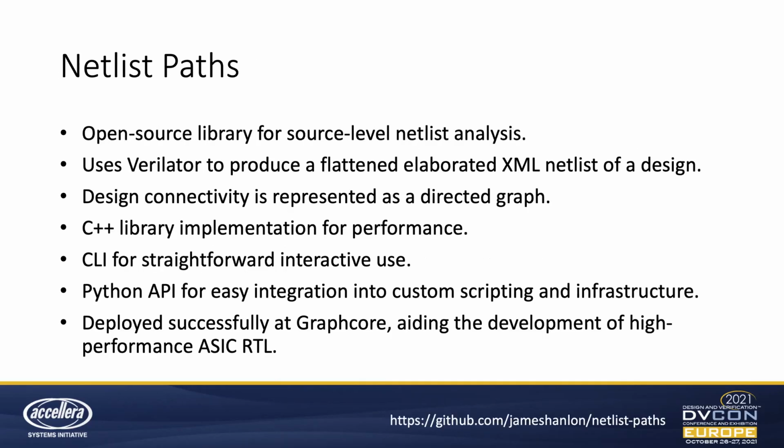So to introduce this tool that we've built, it's open source, and it's built as a library for source level netlist analysis, as I've described. And we have leveraged Verilator to do what we need to do. So what it does is it runs Verilator, and it gets Verilator to produce an elaborated, flattened netlist of the design, and that's produced in an XML format.